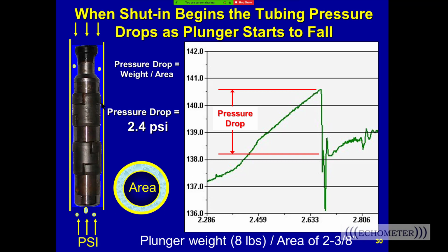So you have to be really careful about running the plunger deeper in the well than you can get the plunger to seal and come back up. Some padded plungers, if you lay them on the side, the pads on the bottom will collapse and then they won't seal anymore. They'll just leak. So you have to be cautious about running the plunger deeper than 40 to 75 degrees. You can get some plungers to work deeper than that.